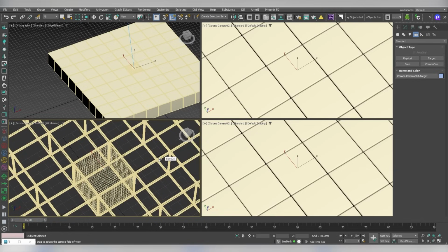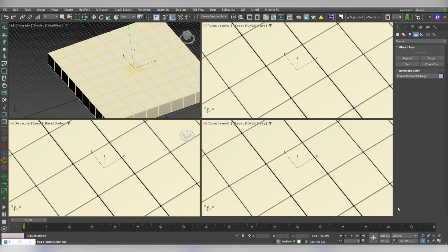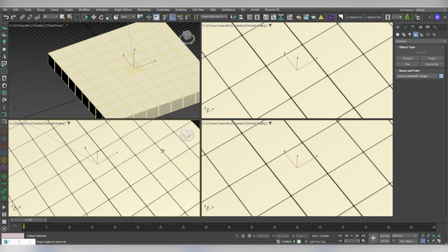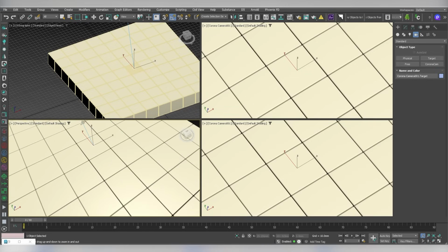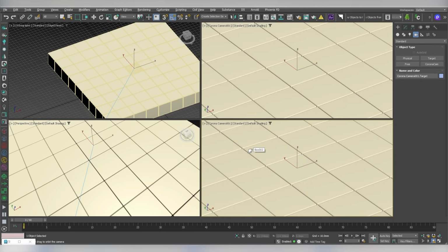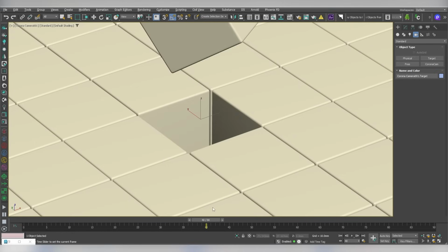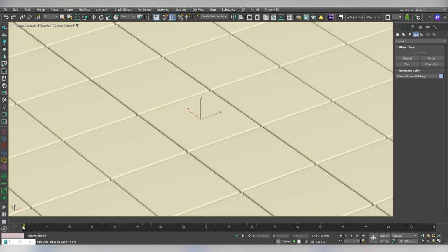Next, press P to switch to perspective view and zoom out. Then move closer to the scene using the mouse scroll wheel. On the left side, you can see the perspective view, while on the right side, it looks more like an isometric view. This example isn't perfect, but it gives you an idea of the difference. Now to adjust the camera, I click on the right viewport, tweak the angle a bit and press Alt W to maximize the window. When we play the animation now, we can see that the main box goes out of the scene as it rises.